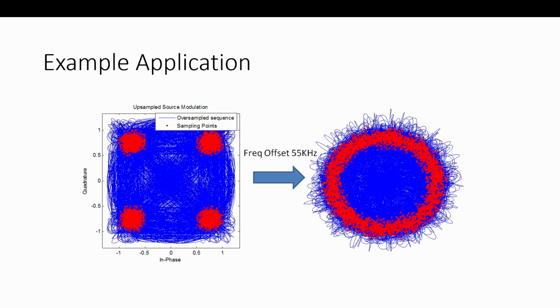That's what you're seeing in terms of the constellation. And then there's a frequency offset, so a carrier offset, a frequency error between what was transmitted and what was received, which will inevitably happen due to Doppler or that we're just running on different clocks. We can't avoid it. So it takes this nice square thing that we could demodulate and spins it. So that's what you're seeing. You're seeing it spin at that frequency offset rate. Make sense?